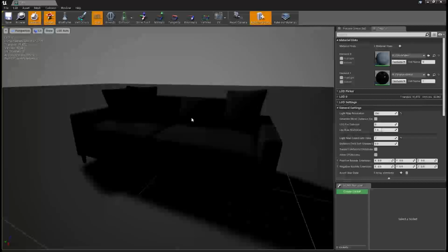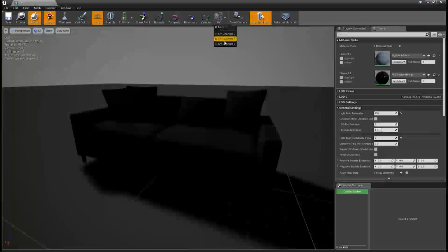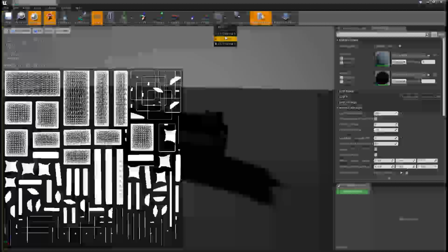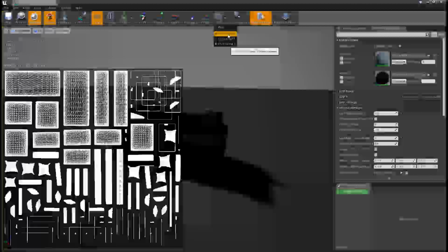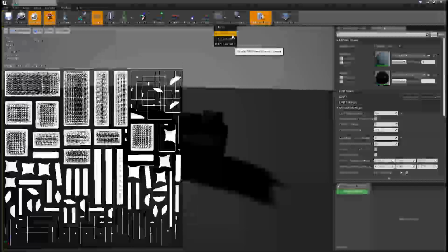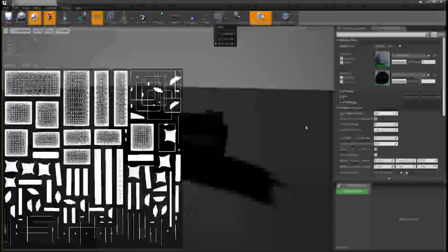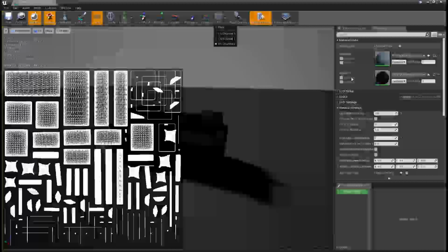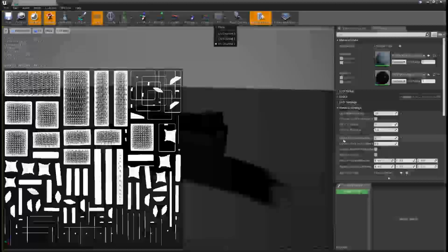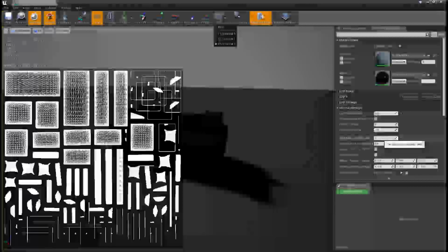So over here in Unreal Studio, we've got the static mesh editor open. We'll go ahead and show the UV channels for channel 0. This is the projection mapping for the diffuse texture. And then we have channel 2 down here. This is our lightmap UV channel. Bear in mind the channels in Unreal are 0-based, so this channel 0 corresponds to channel 1 in 3ds Max. Channel 2 is our lightmap channel, and then over here on the right under details, under general settings, you'll find lightmap coordinate index, and this is where you can specify which UV coordinates you want to use, which channel.